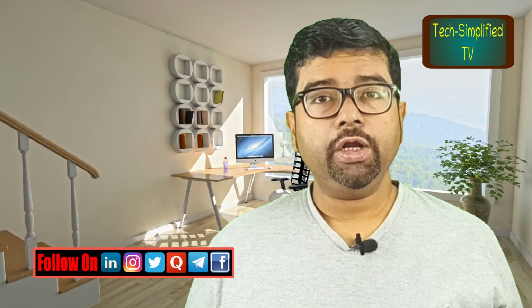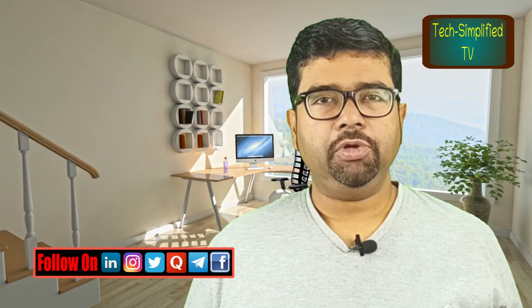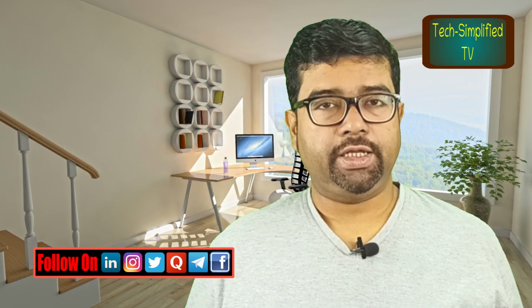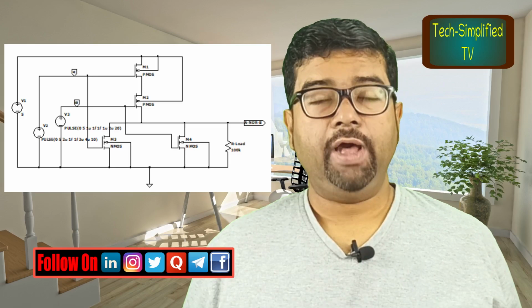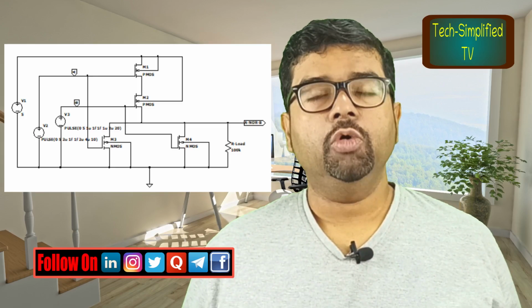Hi folks, you are already familiar with the LTSpice GUI and toolbox. In the last couple of episodes, you have become familiar with basic CMOS logic circuits. In this episode, we will construct a CMOS NOR gate using 4 monolithic PMOSFETs and NMOSFETs, where the PMOSFET has double the area of the NMOSFET for mobility balancing.